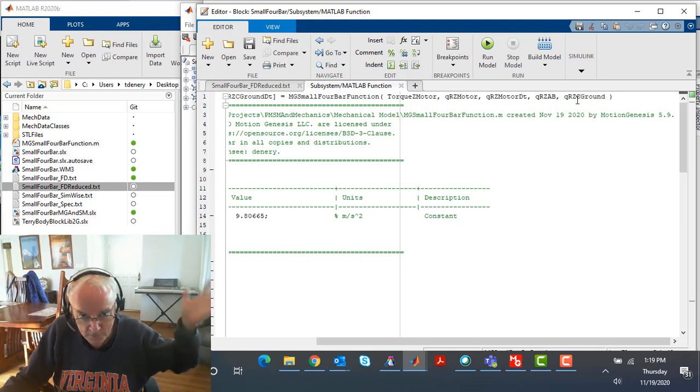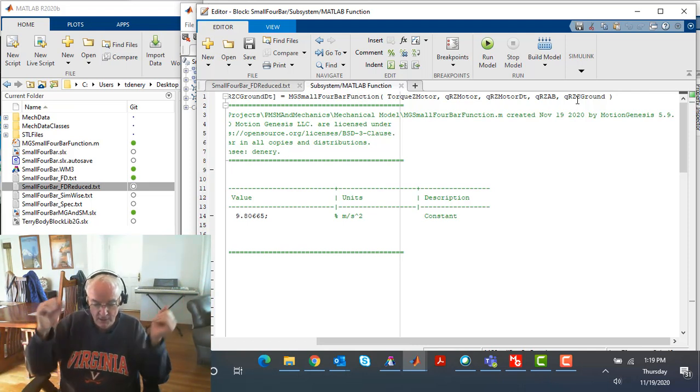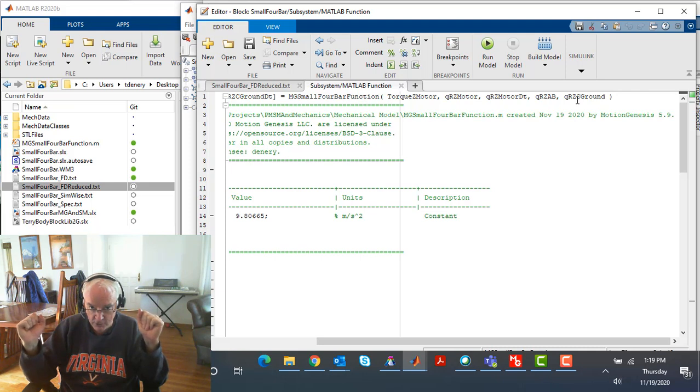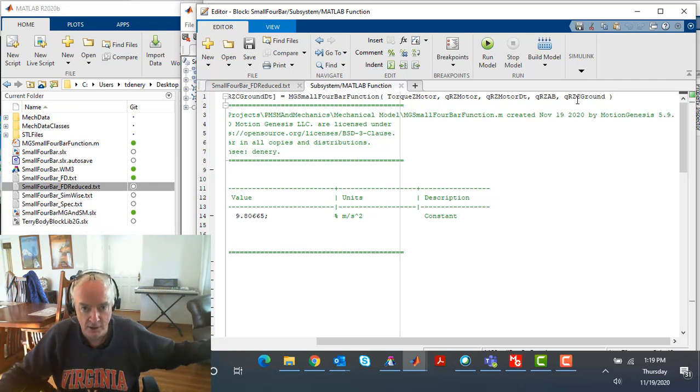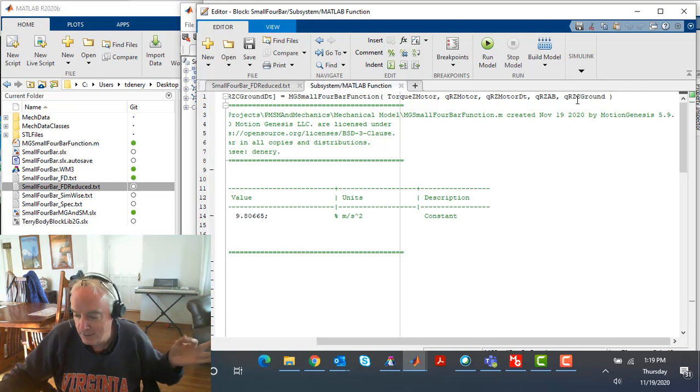And there's this whole dependency issue and dealing with the singularity where the linkage can have the exact same lengths, the exact same joints, and the joints in the exact same locations, but the initialization is set one way or the other. There are two possible results for how this mechanism will move. It's something we talked about in the last video, and if it's confusing at all, go check that out, and also possibly send me an email to let me know. But I think it's explained pretty well.